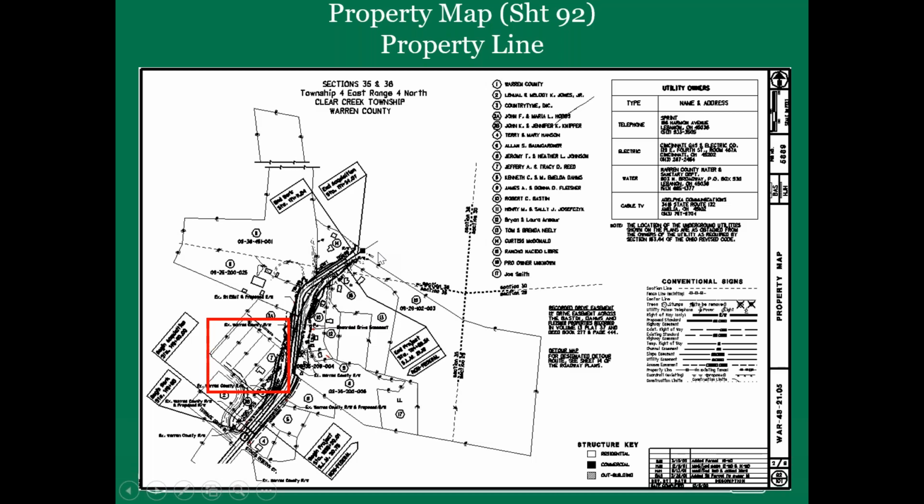I'm going to zoom in here because I want to talk about the property lines and how ODOT identifies property lines. They're identified as a line with a symbol on them, PL. So this is a perfect example. It's a subdivision right here. What I've done is highlight all the PLs. They're along these property lines and they identify what the property lines are. This would be one ownership.